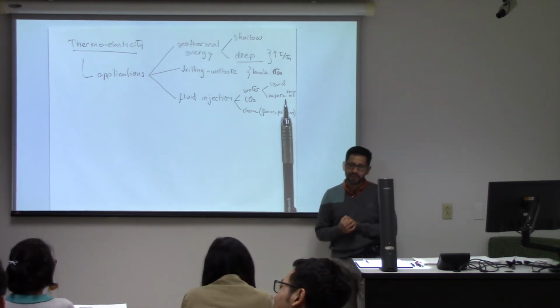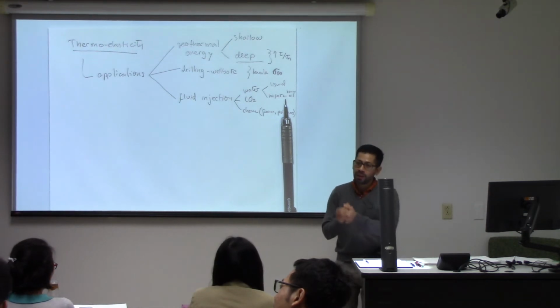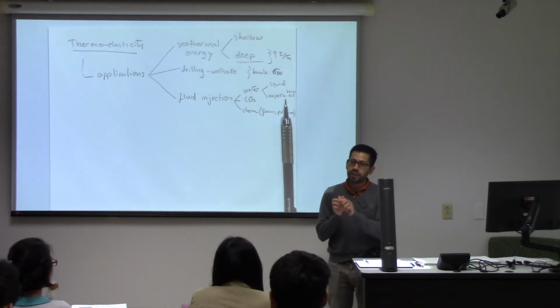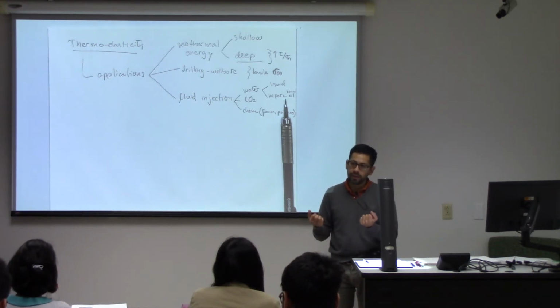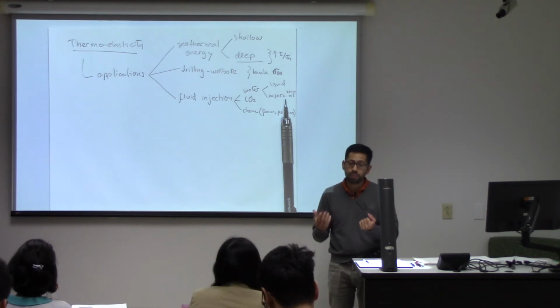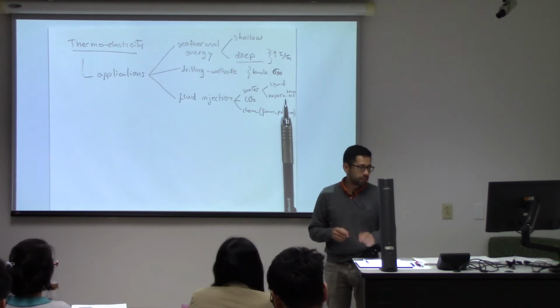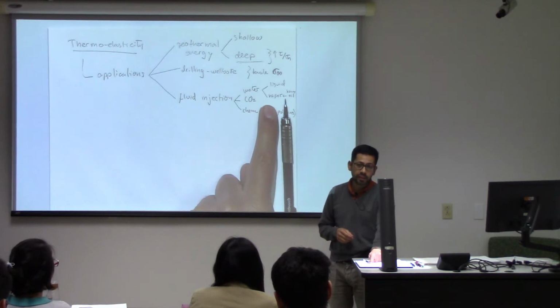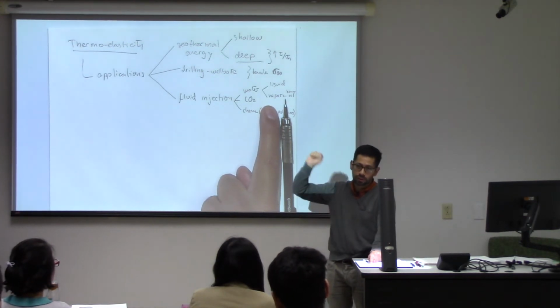Phase behavior, okay. Yeah. But notice that you're increasing the pressure because you're injecting a fluid, but also if you heat up the resident fluids, they're going to try to expand, and some oils may change phase too and go into a vapor phase, and that's going to cause a lot of pore pressure increase. There are some documented cases in which they have geysers on the surface because of not controlling the pore pressure well, so they create outbursts of vapor on the surface.